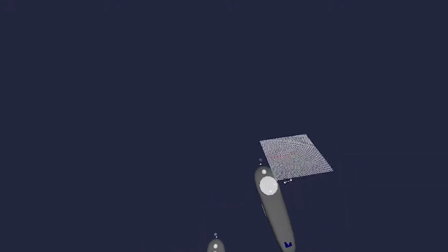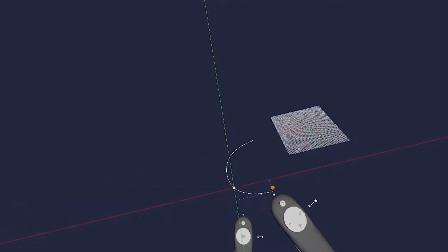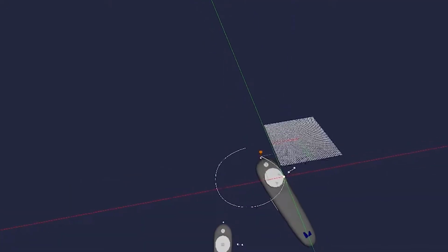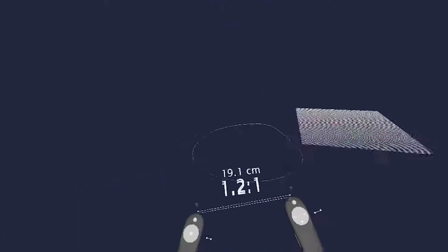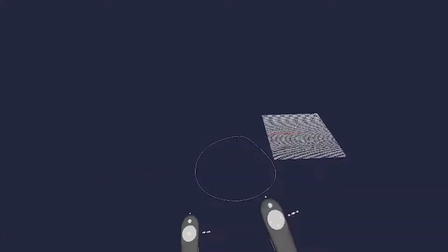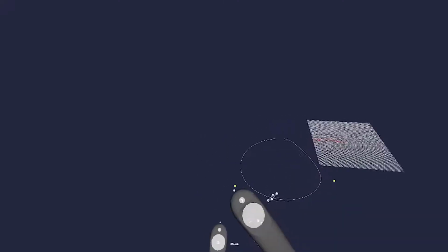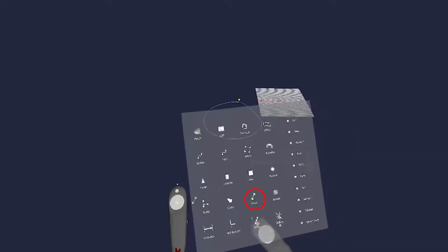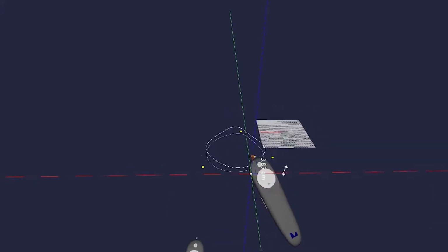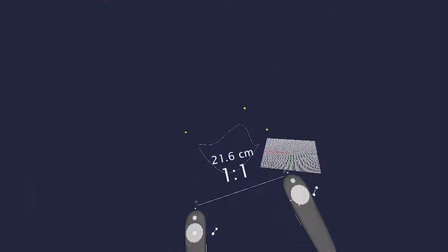Once you launch the app, select the spline tool and create a flat, closed loop. Next, turn on the points and select a few of them that we're going to bring up vertically to create a three-dimensional line. Make sure you stay in line with the Z or blue axes.